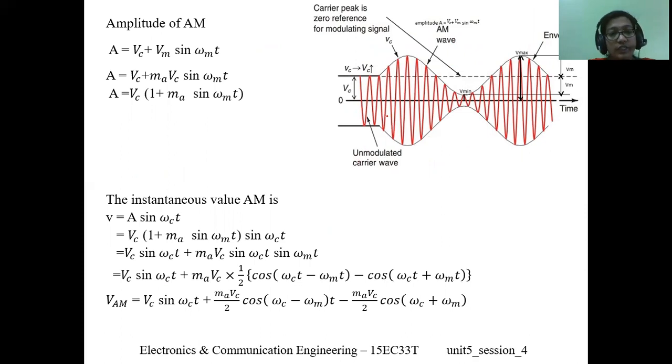This is actually our AM signal, the amplitude modulation signal. Here, this is the carrier amplitude. The carrier amplitude remains the same, because the amplitude of the carrier wave is going to vary in accordance with that of the message signal. We can observe here the message signal forms an envelope of this AM signal, on either side of the carrier amplitude, in both the positive and negative sides.